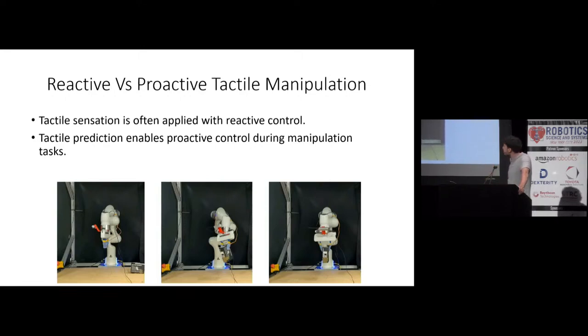In the case of slippage control, that might mean not increasing the grip force because the object's delicate or we're already at max grip force, and instead doing more appropriate control with joint space trajectories or adjusting the grasp position on the object.